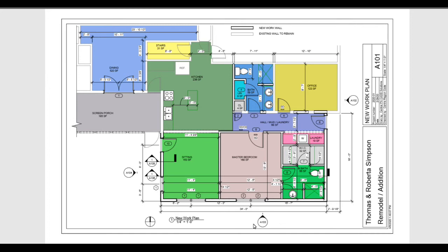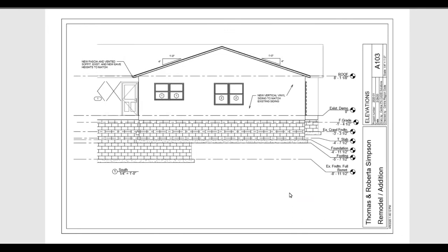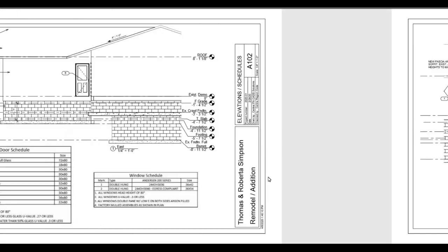This is an elevation symbol that shows up on a plan view, and basically what this does is say to anyone that's looking at it, hey, if you would like to see an elevation of this side of the building, then go to drawing number 1 on sheet A103. So I'm going to go to sheet A103 and look at drawing number 1. You can see that is my south elevation, and it gives me all the detail information that an elevation would typically have on it.